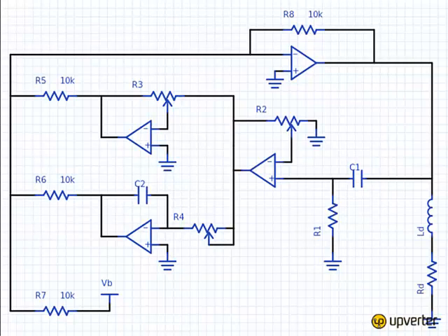The first thing we tried was a proportional and integral control on the velocity, which is equivalent to the control we were using in Simulink. The voltage on the inductor should be proportional to the velocity of the magnet. So we put that through a high-pass filter, C1R1, to bring that into our circuit so that we didn't have to deal with the DC bias.